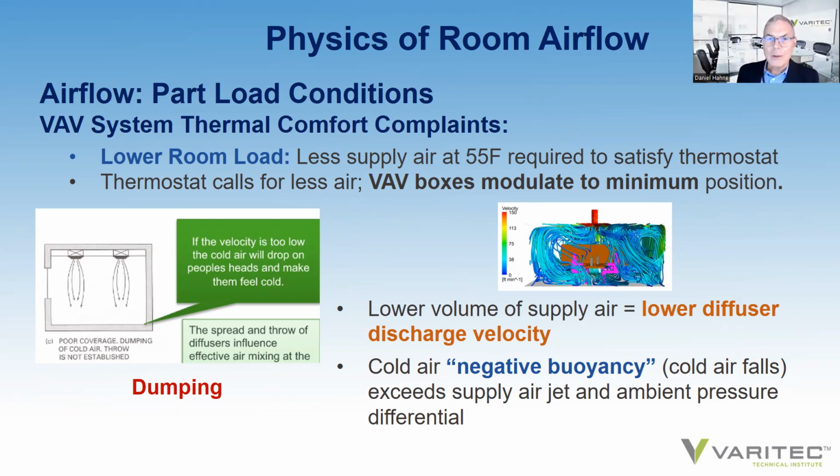So this is a condition in a lot of institutional buildings with VAV systems, even office buildings, a lot of larger office buildings especially, that you do not have the proper discharge out of a diffuser, or discharge velocity, to maintain a properly mixed environment that will allow for a more effective dispersion of contaminants released into a space.